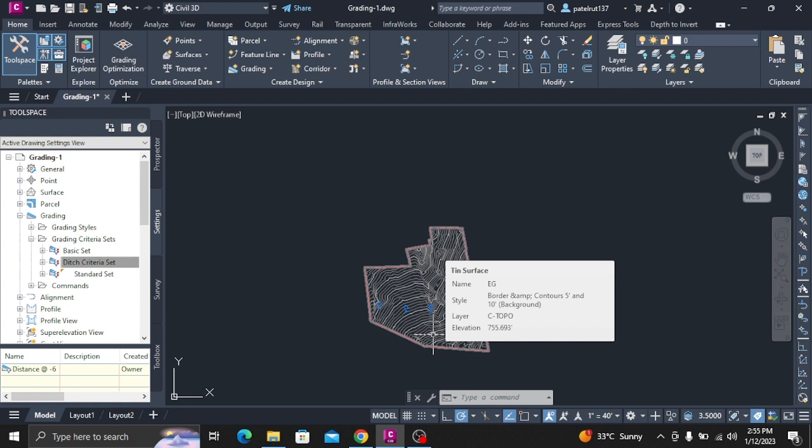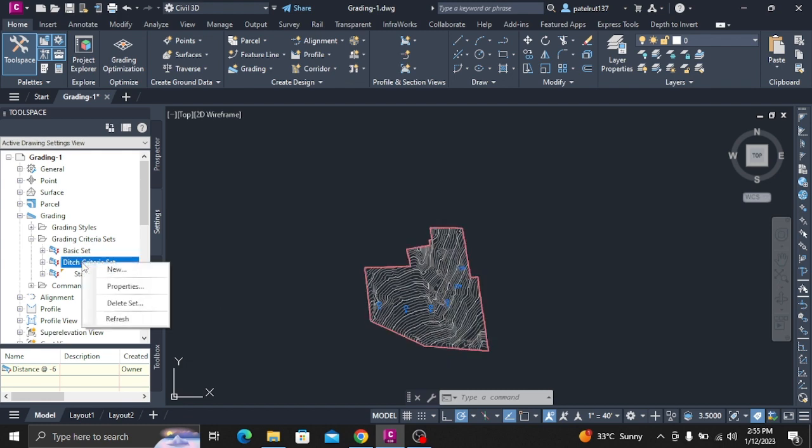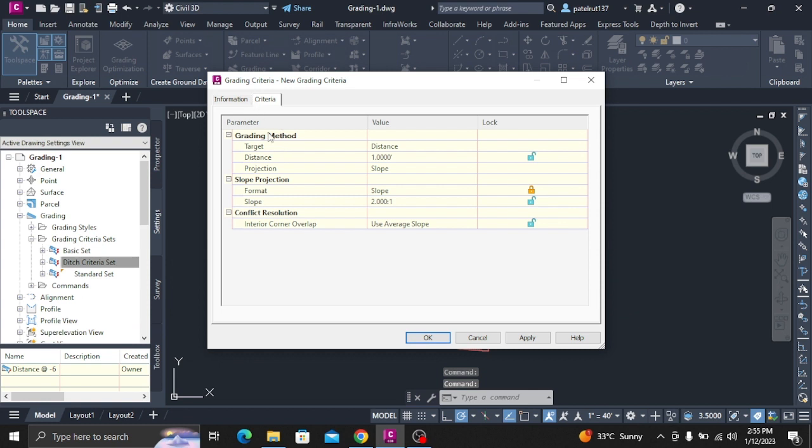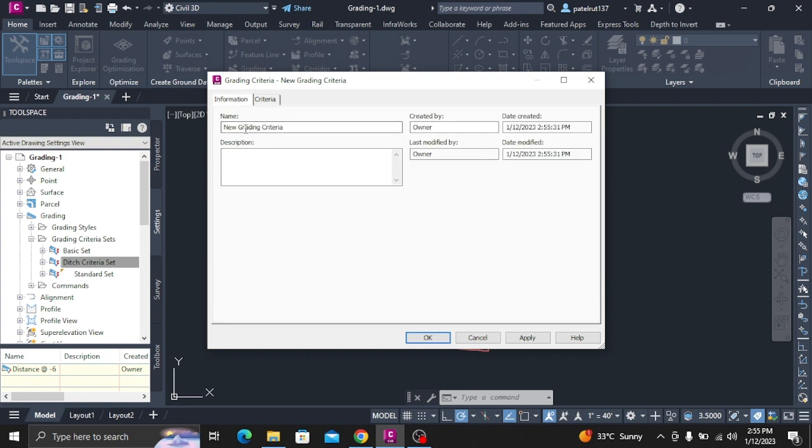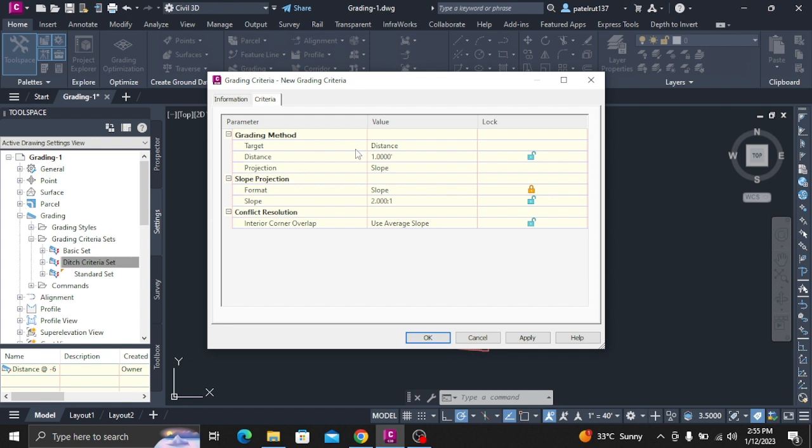Click the Slope Patterns tab. Select the Slope Pattern checkbox. Select the Basic Style. Click the Style drop-down list and click Copy Current Selection. In the Slope Pattern Style dialog box, on the Information tab, change the name to Ditch Slope. On the Layout tab, in the Component field, select Component 2.